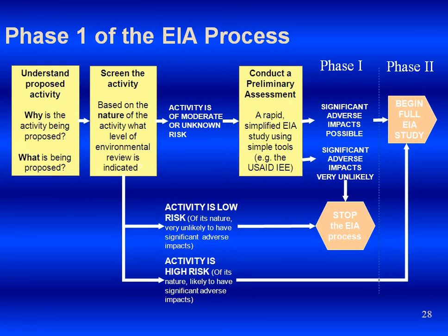Now we have already covered understanding the proposed activities, why and what. Then you screen the activities: to what level of EIA is required, or not required. If a moderate or unknown risk is there, in that case you go for a rapid, simplified EIA study, using simple tools. So they go for a rapid EIA to carry it out.